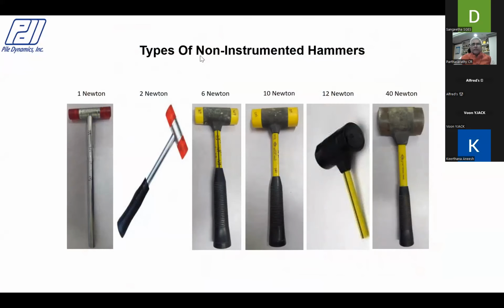Now, it's also important that you calibrate the hammers, because one size doesn't fit all. So we have piles from 300 millimeter diameters to 3 meter, maybe even more for monopiles. The length of a pile could be just a short stub pile of about 1.5 to 2 meters to as deep as 70-80 meters, which in this country is not uncommon. Therefore, you need to calibrate different hammers and use a hammer that gives you consistent results and also the toe response.